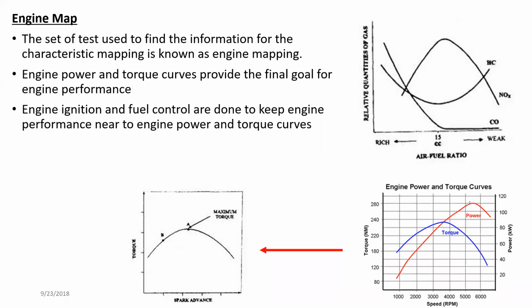But it's possible to change this by changing the fuel supply and ignition timing. These can be changed a little bit, right? So if you know what sort of vehicle it is and where you want to drive it, what sort of driving you are expected to do, based on that the power and torque curve can be identified.